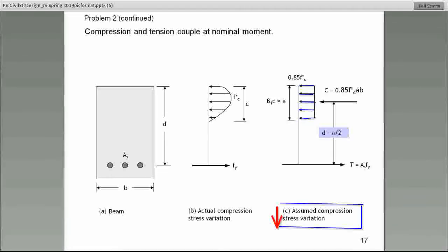You know, last Thursday, I started the presentation by giving you an equation that helped us find the stress. Given the force, how did we find the stress? The very first equation was an axial stress. Those of you who said sigma is equal to P over A, you are correct. Stress was load divided by the area.